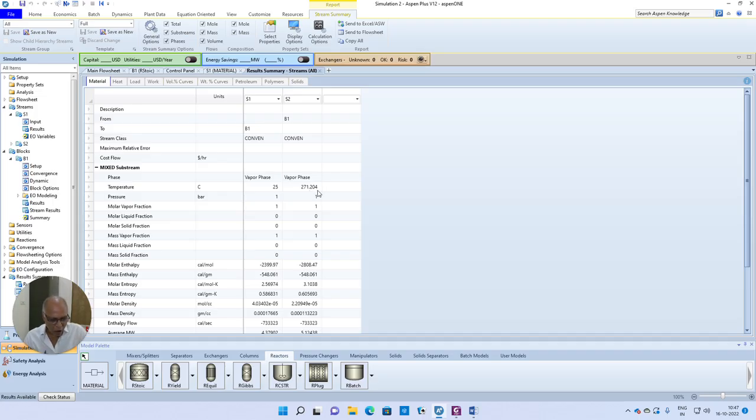Even when 80% of carbon monoxide is converted, the amount of heat liberated will be similar to what you had seen in the previous case, right? Now the same amount of heat has to be utilized to heat a larger amount of fluid, the reaction mixture. Now there is a lot of hydrogen. That's why the temperature is coming down.